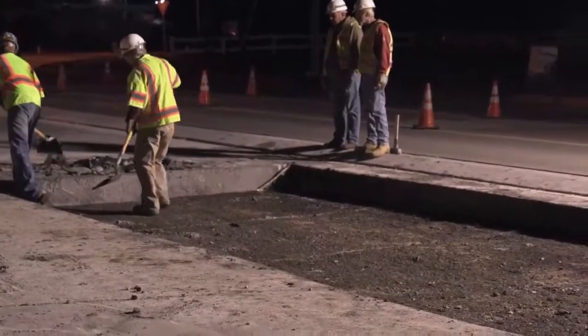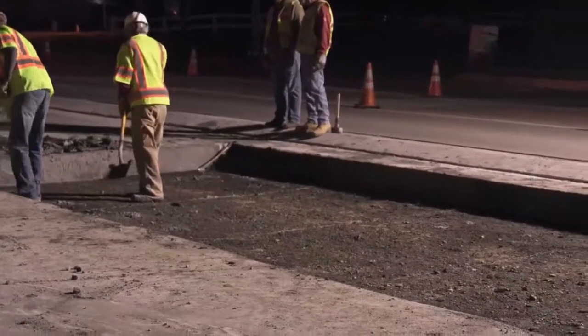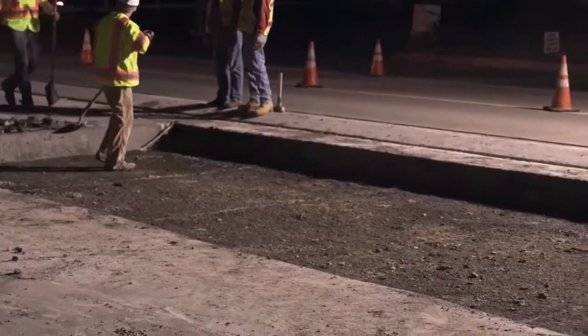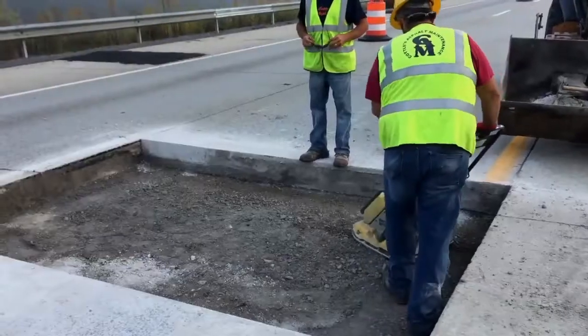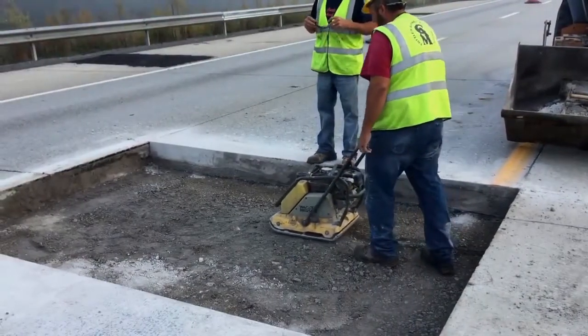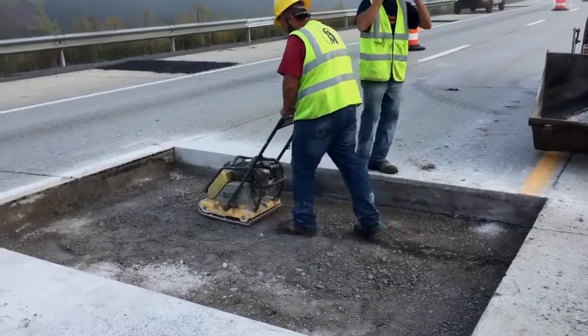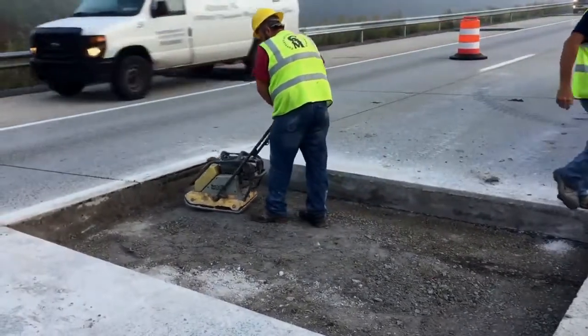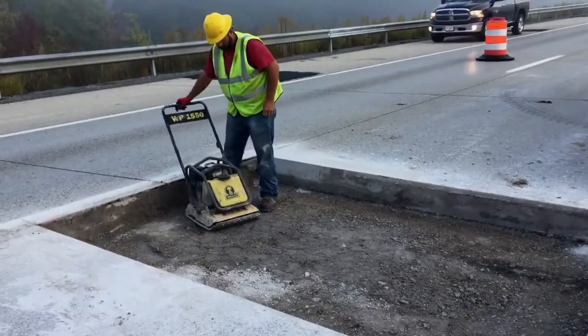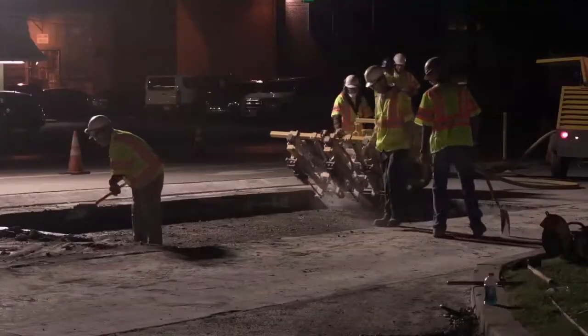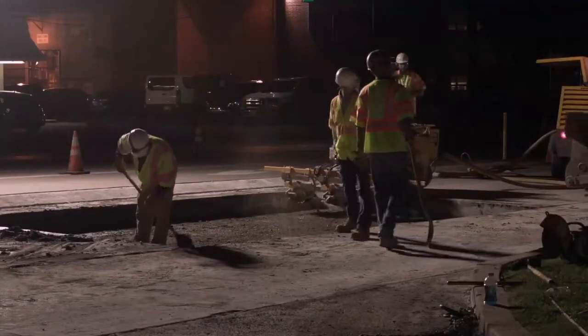Repair area preparation. It's important to try not to disturb the subbase material as much as possible. If the surface area of the subbase is disturbed during removal operation, recompact the surface of the subbase using small vibratory compactors. This next step is a very important one.